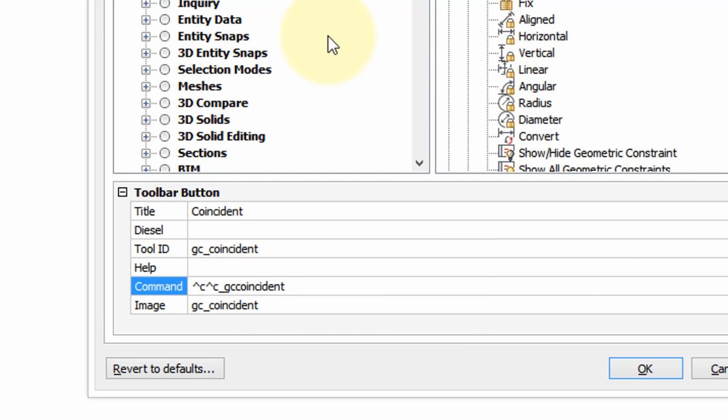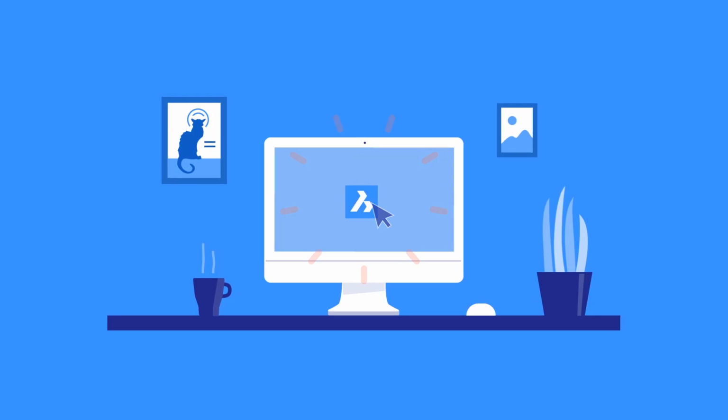Now you can change them. You can add more commands to it, such as two commands in a row. All you do there is type a semicolon. That's like pressing the Enter key to continue the command, and then you put in the rest of the code. Now what you put next varies greatly by the type of command, and that's beyond what this video can cover.